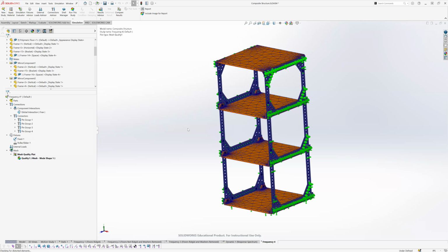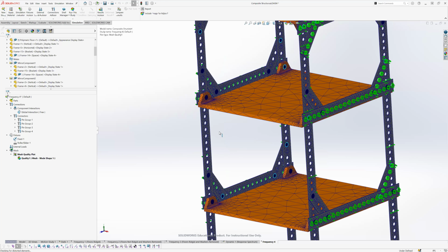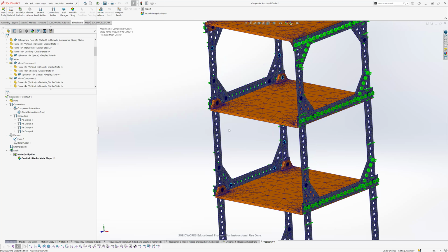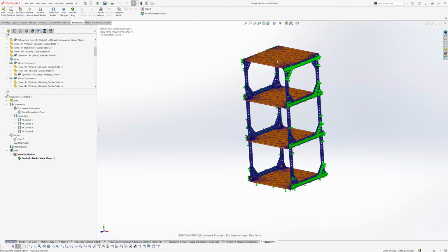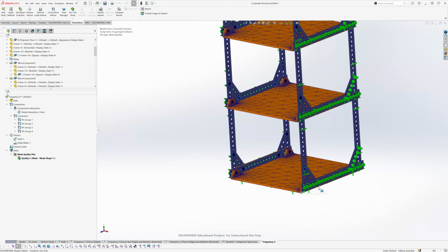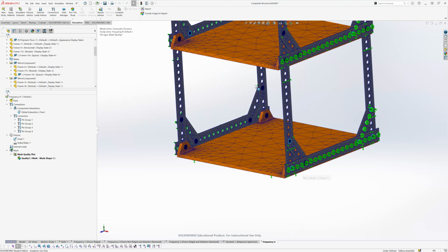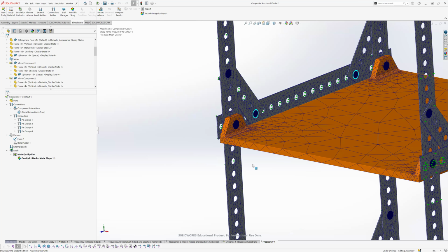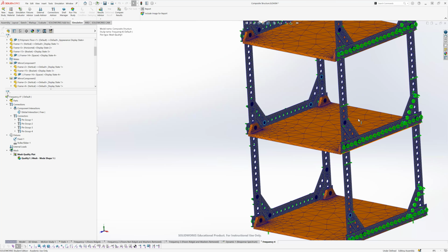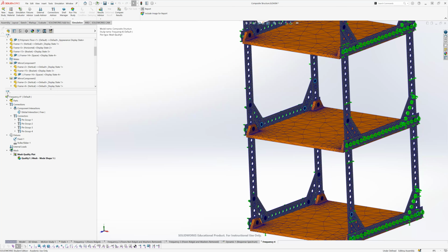Okay, so one thing also, since I think this is the first time in these sessions I've talked about making something a rigid body: a rigid body is actually still meshed, but if you notice, rigid bodies are colored in orange, so that tells you it's treated as a rigid body. So that's good to make sure everything's consistent. Make sure all of our frames are not rigid and make sure these are rigid, because that's what we defined. So this is another great way in the mesh to check everything and make sure everything is looking as expected.